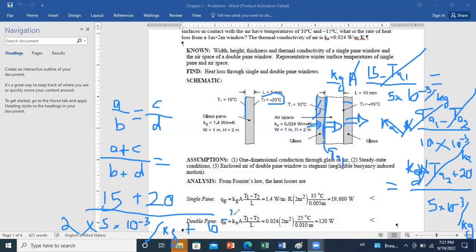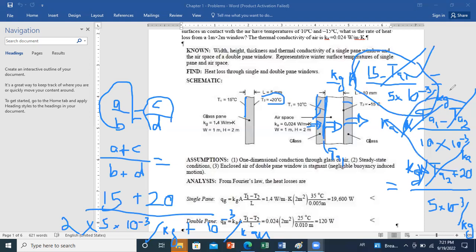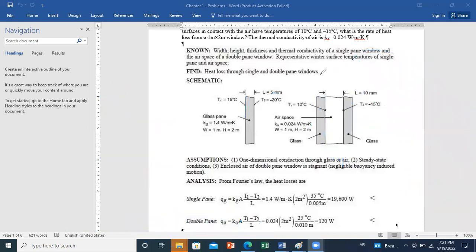So now you know that this factor is equal to A over B and is equal to C over D. Now you can take this equality with this term, you can get the value of TA1. When you equate it with this term, you will get the value of TA2. So this will allow you, by just doing the analysis of steady conduction flux, to determine these temperatures.